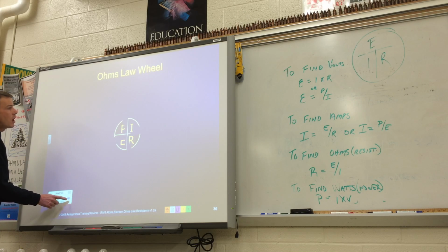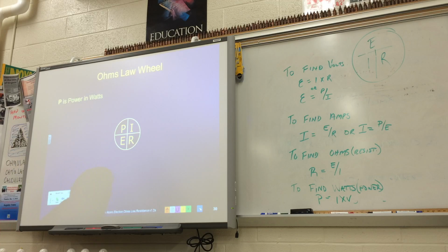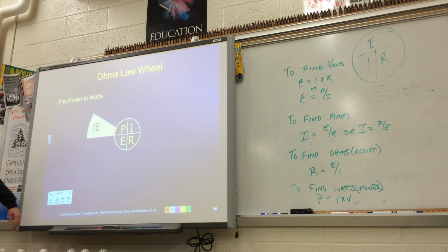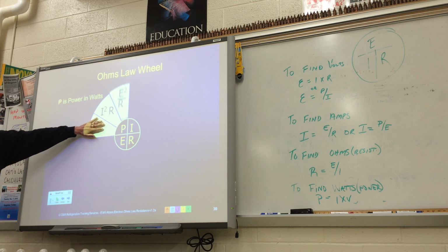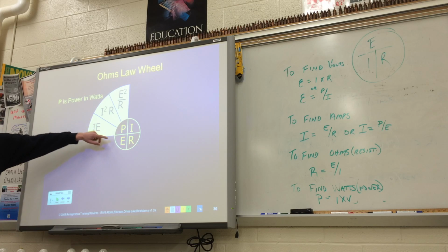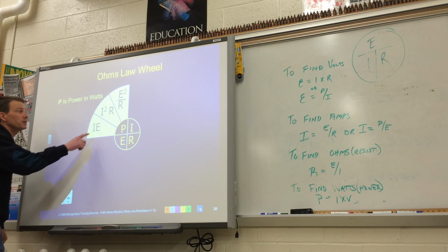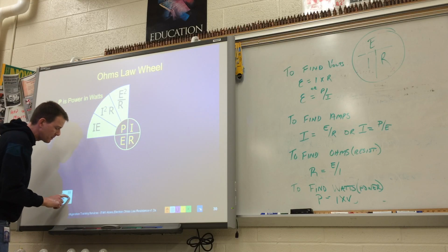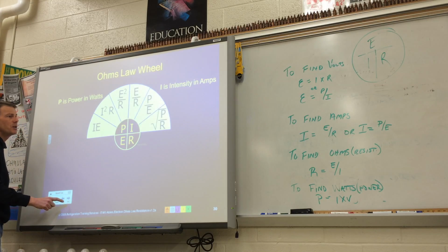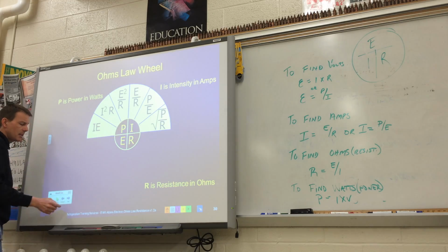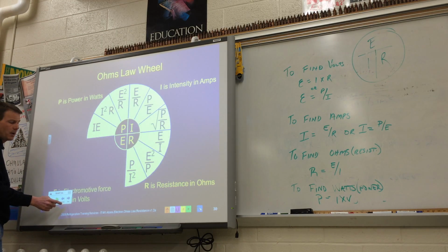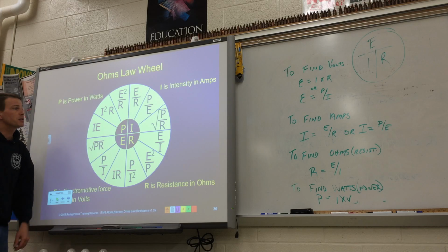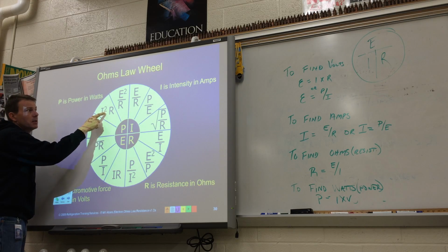All right, so look, Ohm's law. I showed you one wheel. One wheel had just E, I, R, but we also can incorporate power, or expressed as watts. This is the way I just showed you, a simple way of finding it. You take the volts times the amps, that lets you know what the watts is, okay? But if you don't have the volts and the amps, you might have resistance or amps. You can do it another way. We don't need to memorize this particular wheel, because I can show you a way that you can do it if you just had the E, I, R to still calculate for power, providing you got 2 of the 3. But the wheel gets bigger because they're adding power to it. And now they're going to start using the square roots or the squares to find out some of the stuff.